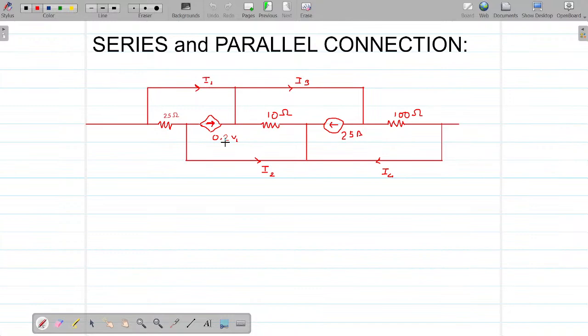Because in network theory, it is very important to understand what are equipotential nodes, and only when you can identify equipotential nodes will you realize how important it is to solve questions and how much easier it makes things. What appears to be a difficult question to handle, I'll tell you in a few minutes how it becomes a simpler question to solve.